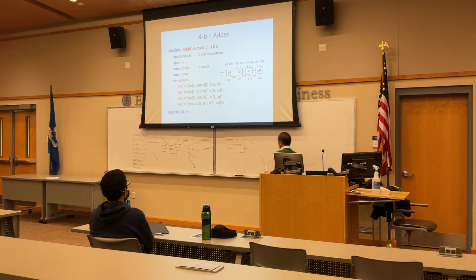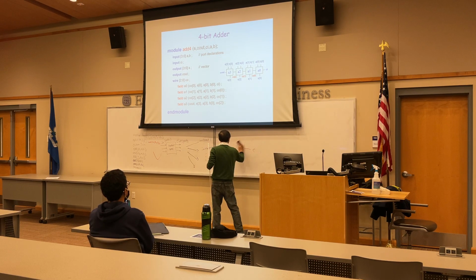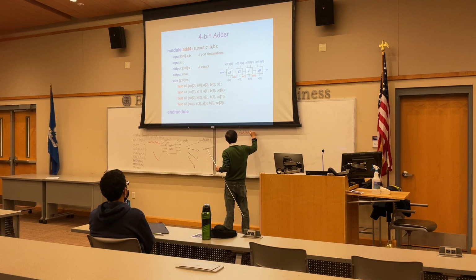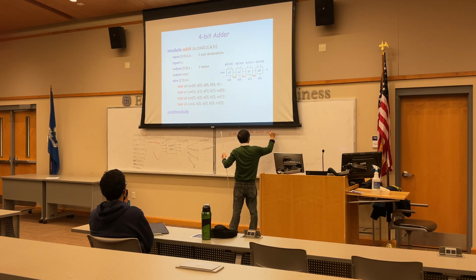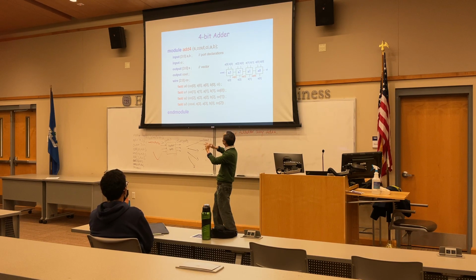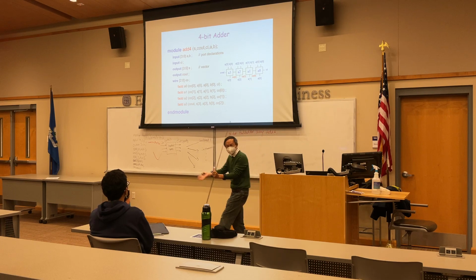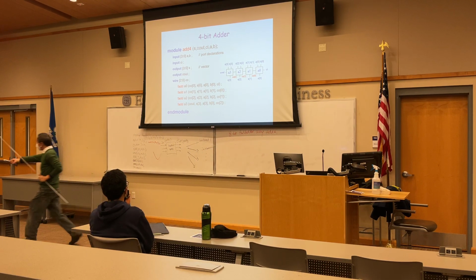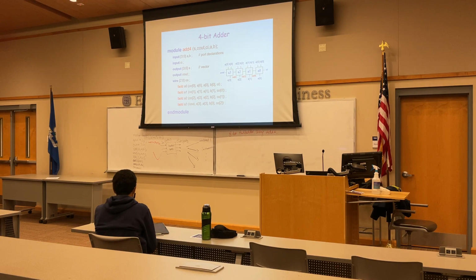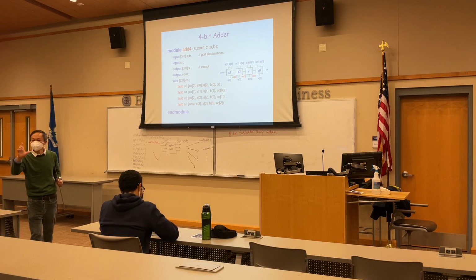I'm going to invite you. Follow this example. Can you design an 8-bit full adder using this 4-bit adder, ADD4? We designed it just now. Just call the instance. I'm going to challenge you, right? Step by step, we get a bigger circuit. Would you like to help us? Okay. And everybody, I challenge you, I want you to give a try. Follow this example, and you just need 2 instances, right?